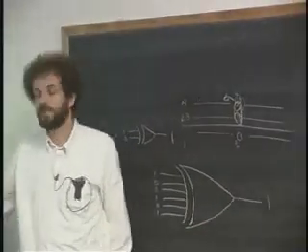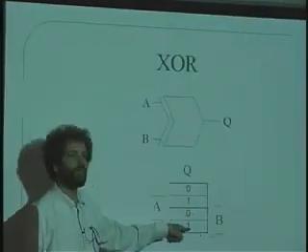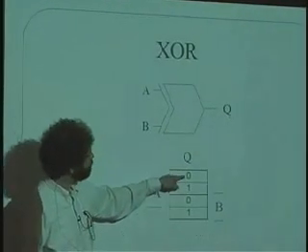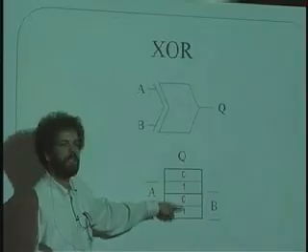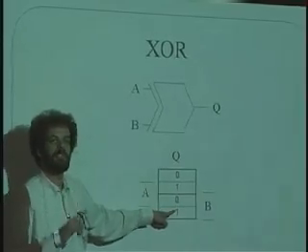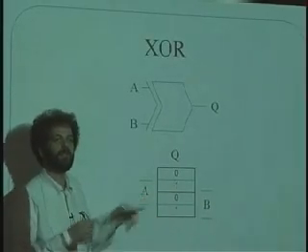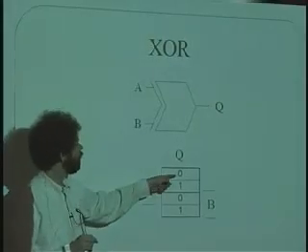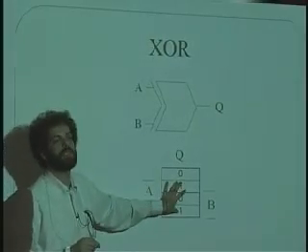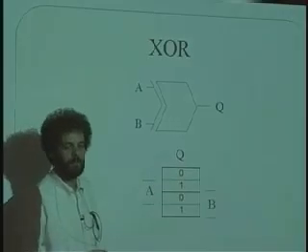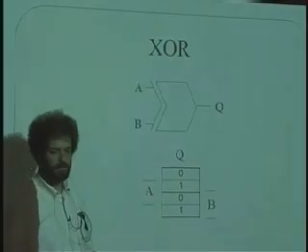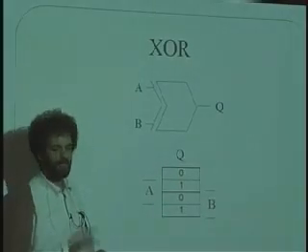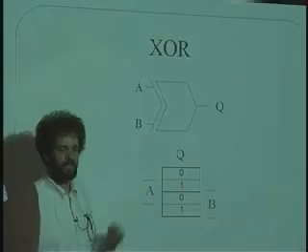And that's why when you look at a K-map of something that has XOR in it, you always see this checkerboard or chessboard type thing where it goes 0, 1, 0, 1. Why? Because in the K-map, as you move from one square to the next, exactly one input is changing. And you know that the XOR of something where one input changes switches from 0 to 1. So it has no choice but to act like this. So if we had 3 or 5 or some odd number of wires coming in... We're actually going to look at that. Okay. Then you'll get to see what it actually looks like.